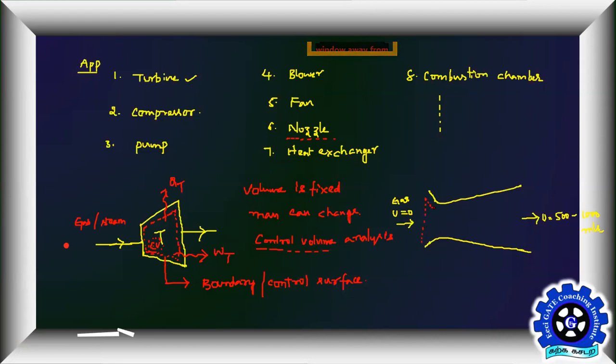You want to enclose this gas when it is coming inside these solid surfaces as your system. Are you guys following what I am telling you? This is your control volume. Is it an open system or closed system? Open. Why? Both mass and energy transfer take place. It's a straightforward statement. You see some mass coming in, doing something and going out, and during this mass interaction, you will see some energy interaction also, some in the form of heat.